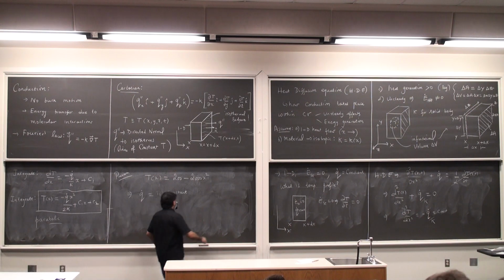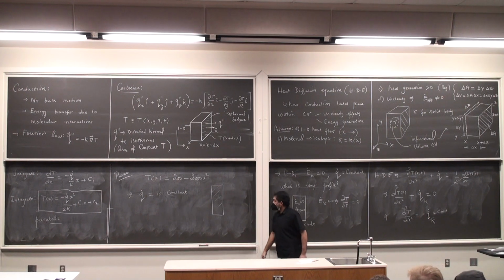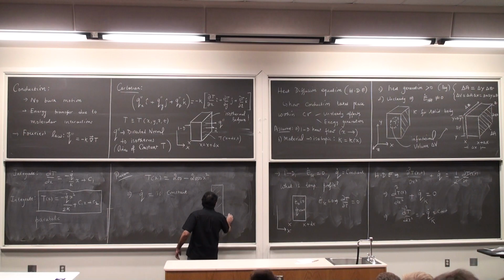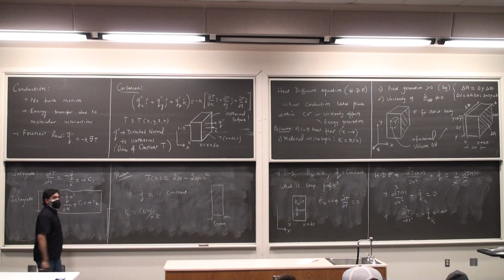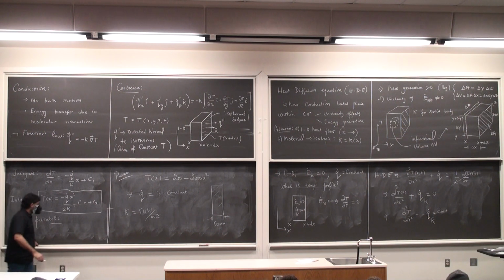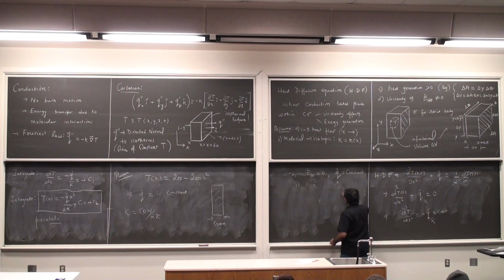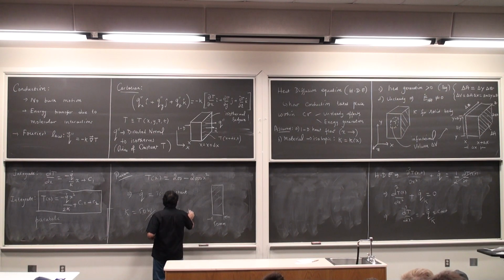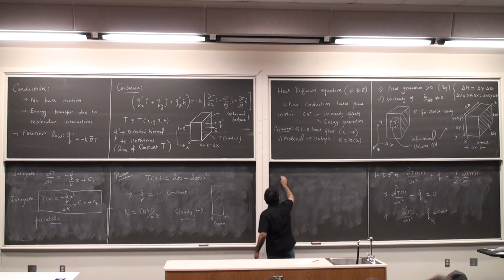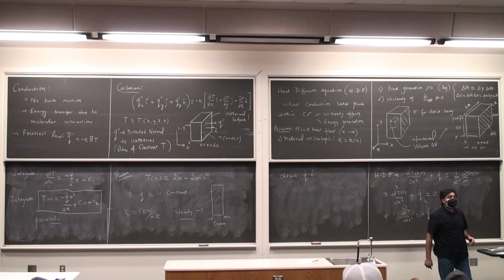You're told that this is the temperature profile through a solid brick. Okay, I'm not going to draw that yet. Thermal conductivity is given to me, thickness is given to me. 50 mm, and then K, 50 watts per meter Kelvin. Determine Q dot in steady conditions. Obtain Q dot, and we will also sketch the temperature profile.